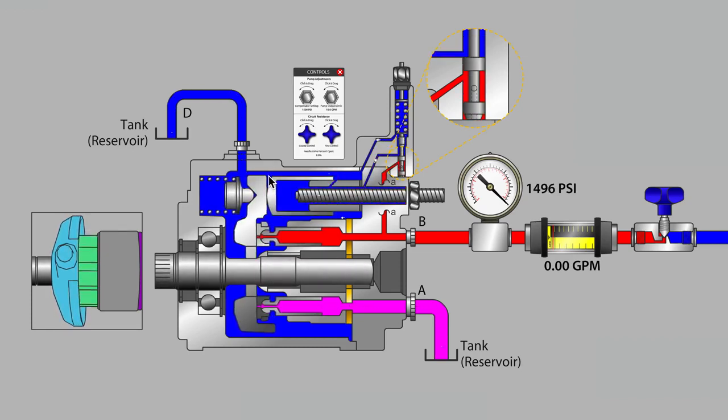One additional source we should point out here just before we close off is that in order to keep the control piston from driving the swash plate right over center, which would be a very damaging circumstance, to limit the travel of the swash plate once we reach the zero point, quite often a bleed orifice is present on a tube where the control piston is sliding back and forth. So that's another clearance inside the pump where case drain flow originates from.